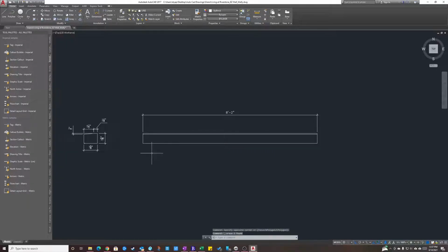I'll show you. You take your offset tool and you start on one side, either end. It doesn't matter which end you start from. So you click your offset tool and it's asking you right there on your cursor, specify an offset distance. Well, the offset distance that you are specifying is the dimension that we just came up with.